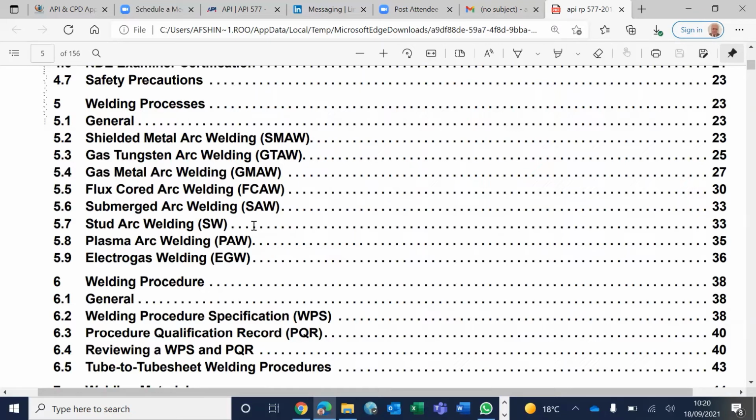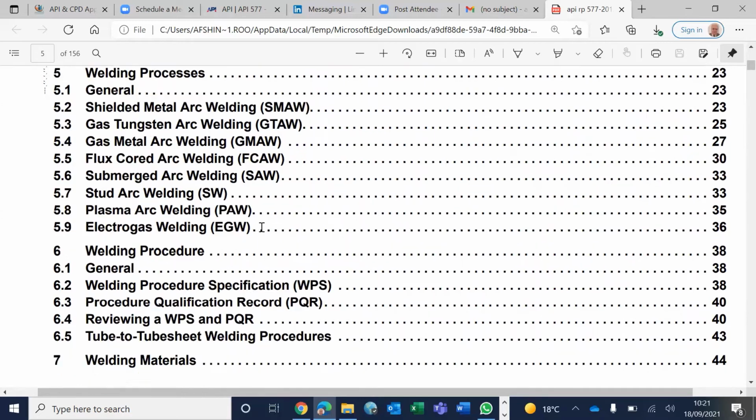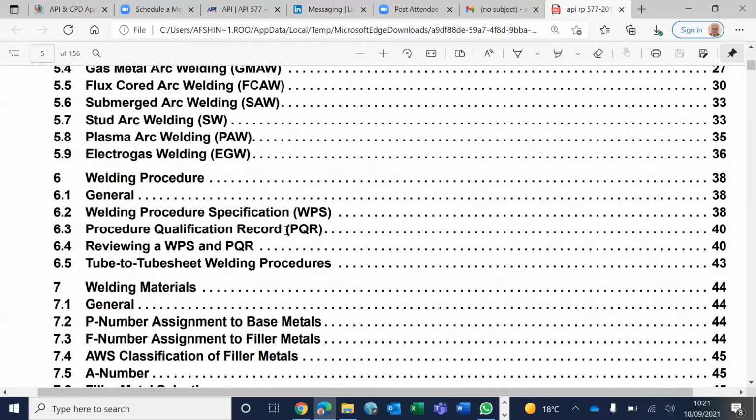It's normally a tensile test, and then if toughness is a requirement, then it's a Charpy test as well, or heat input that needs to be checked. And you should know how to review a WPS and PQR. What you need to look at is very basic things. It would be a single process, tube to tube sheet welding procedure. What's the qualification for that? And the WPS is a fillet weld, or is done on a heat exchanger and boilers.